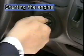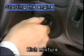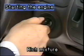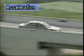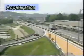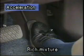Now let's consider different driving conditions, beginning from when the vehicle is started. Naturally, the engine is cold, making it harder for the fuel to be atomized. This alone is enough to create an improper air-fuel mixture. Hence, it is necessary to provide a greater ratio of fuel to air. Next, when the vehicle is accelerating, we know that fuel is heavier than air. So since the amount of air is increased when the accelerator pedal is pressed, the amount of fuel also must be increased to obtain sudden acceleration.